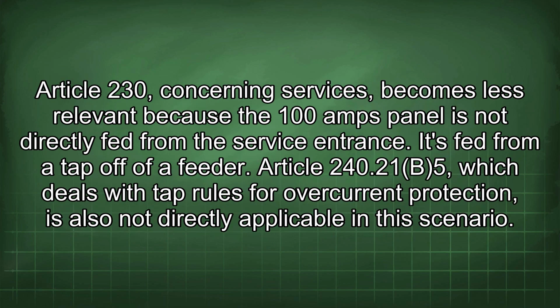Article 230, concerning services, becomes less relevant because the 100 amps panel is not directly fed from the service entrance. It's fed from a tap off of a feeder. Article 240.21(B)(5), which deals with tap rules for overcurrent protection, is also not directly applicable in this scenario.